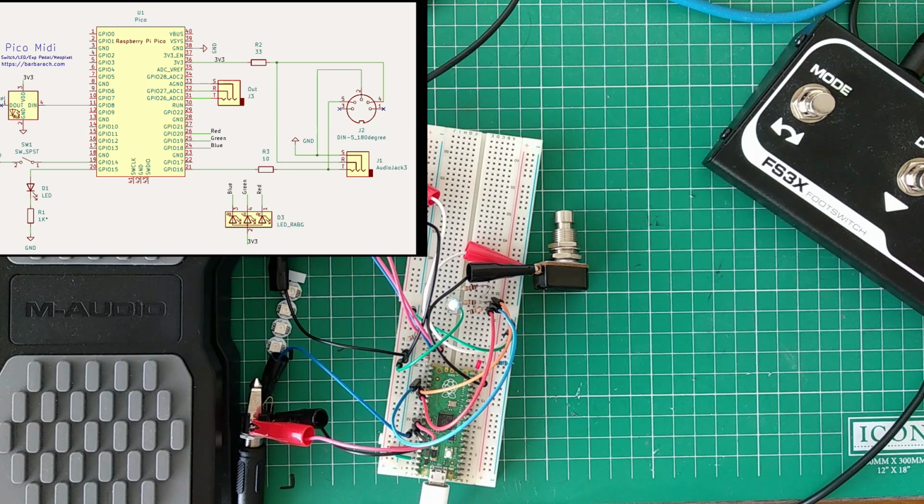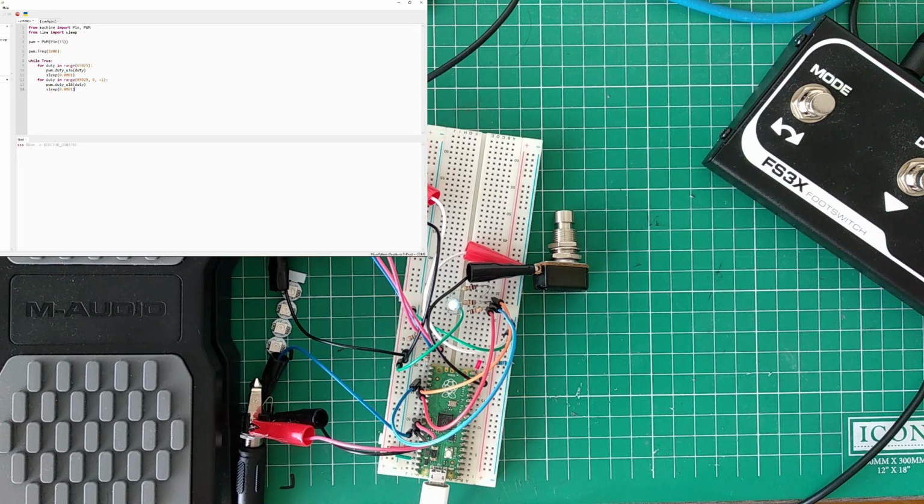So the drop might not be enough to even light them up. Actually, because we are using lower current, the drop is smaller, so we should be fine. But it's one of those things where you have to look into the datasheet and make sure you select the correct diode for the job.